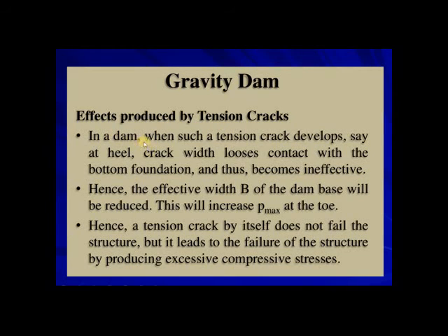Effects produced by tension cracks in a dam. When such a tension crack develops, say at the heel, the cracked width loses contact with the bottom foundation and thus becomes ineffective. So the effective width B of the dam base will be reduced.